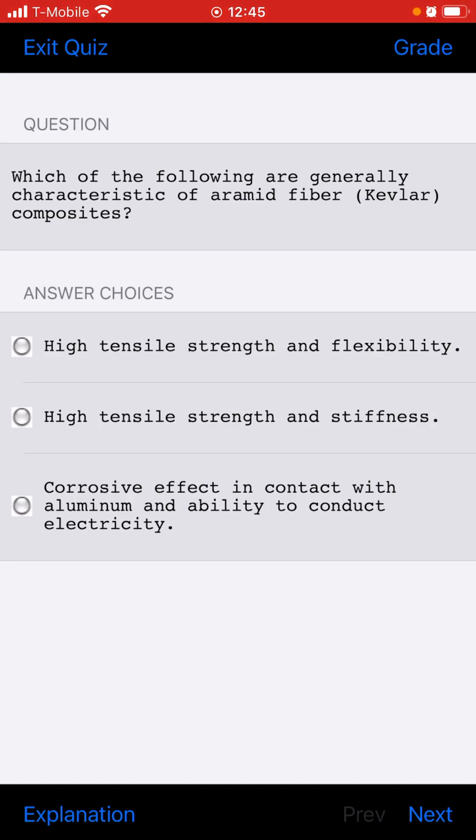A sheet metal repair is to be made using two pieces of 0.040-inch aluminum riveted together. All rivet holes are drilled for 3/32-inch rivets. The length of the rivet that should be used is 1/4 inch. Gotta come back to this one.